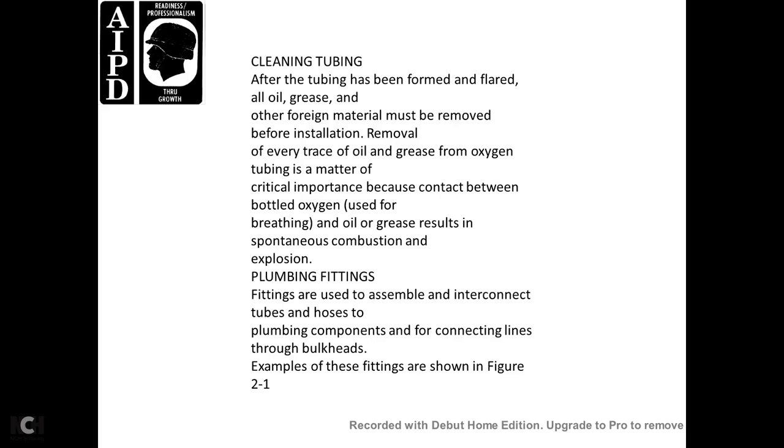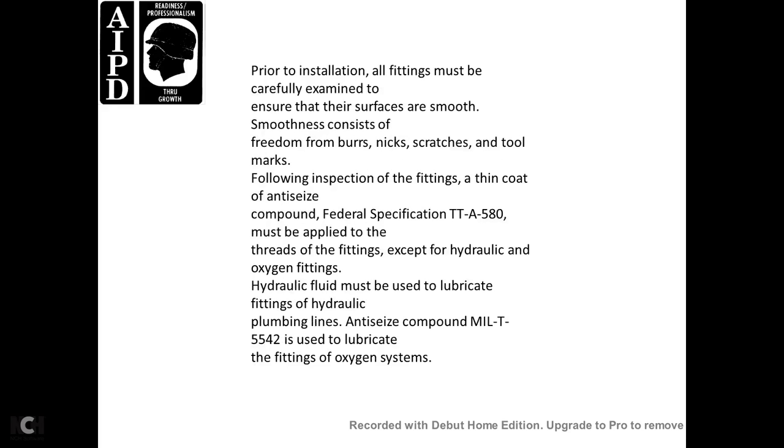Plumbing fittings. Fittings are used to assemble and interconnect tubing, hoses, and plumbing components in connecting lines, including through bulkheads. Examples of these fittings are shown in Figure 2.1. Prior to installation, all fittings must be carefully examined to ensure that the surfaces are smooth and free of burrs, nicks, scratches, or tool marks.